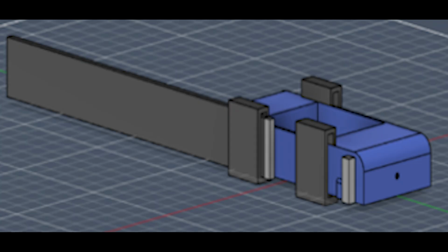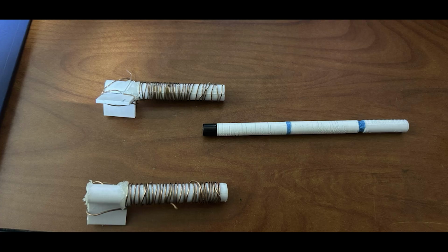Electromagnetic damping. We also investigated electromagnetic damping using magnets and copper conductors. The original idea was to use magnetic resistors generated through relative motion between conductive materials and magnetic fields. Although the magnetic effect alone was not strong enough to significantly slow the impact, testing revealed the friction generated between sliding rods and outer structure provided useful damping behavior.